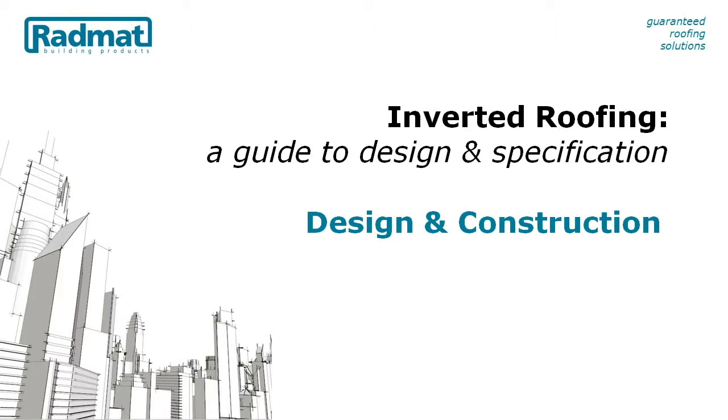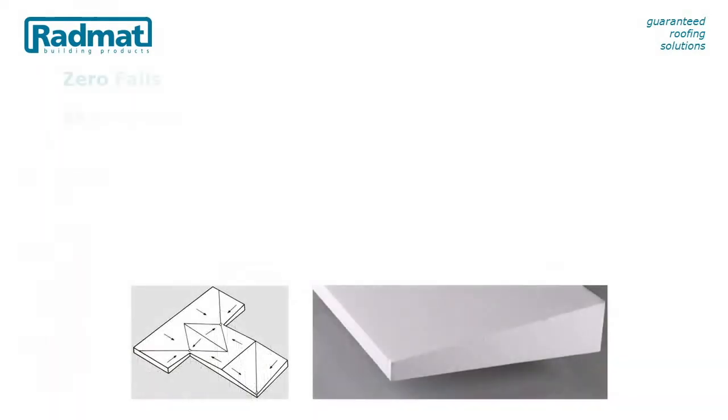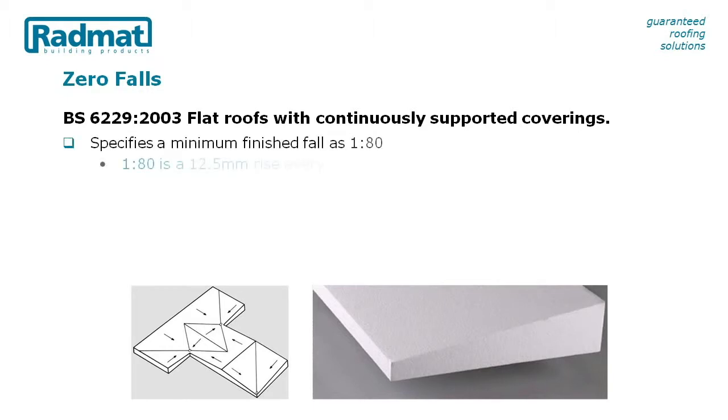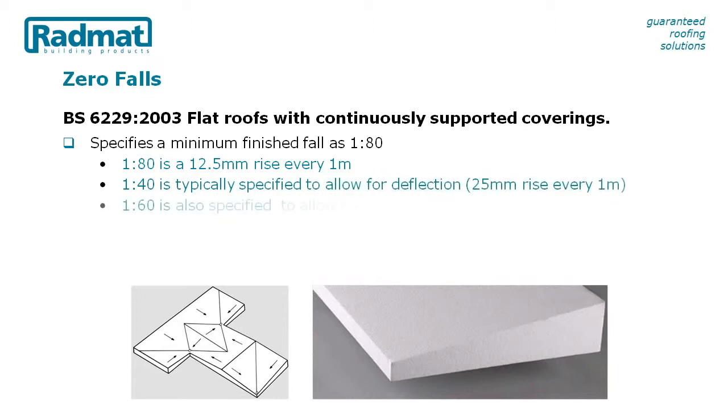Having moved into design considerations, now would be a good time to address what can often be the elephant in the room, namely whether or not you can design and install a roof to zero falls. BS 6229:2003 is the document that the building regulations refer to when it comes to falls on flat roofs, and BS 6229 specifies minimum finished falls of 1 in 80 achieved by designing to 1 in 40.